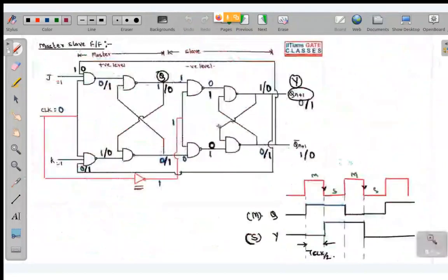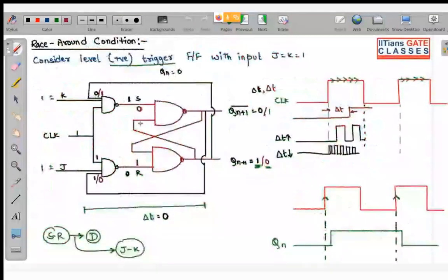So for that only we have this master slave. In any package you take, if you have a JK flip flop, you get the combination of master and slave only. If in the first class I had explained that all the flip flops are constructed using this configuration, you might have got confused. So when we are learning something, we keep the concept very simple and then gradually we increase the concepts. This was the highest level of concept that I had to give you. And remember, all the practical JK flip-flops are constructed like this only. You won't be seeing any JK flip-flop like the simple one.